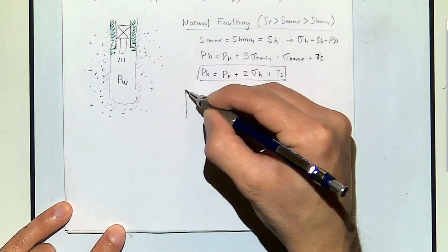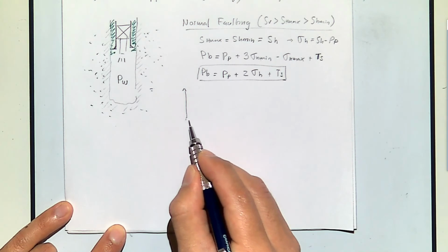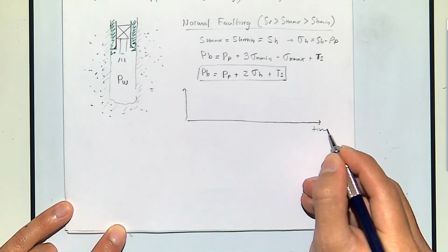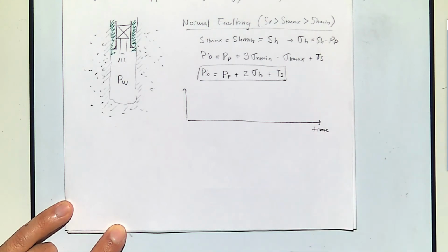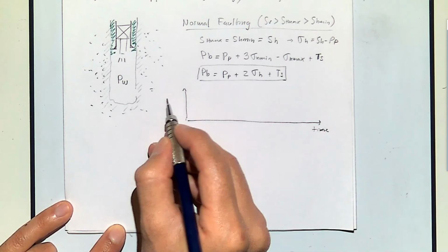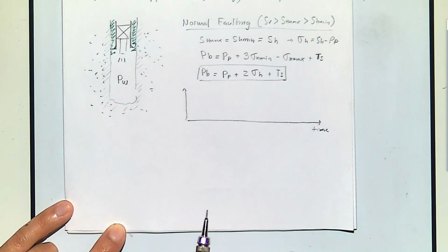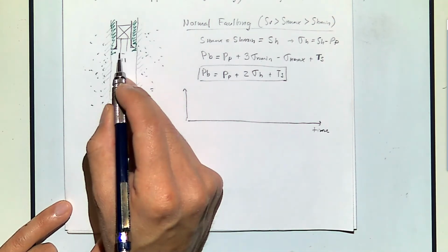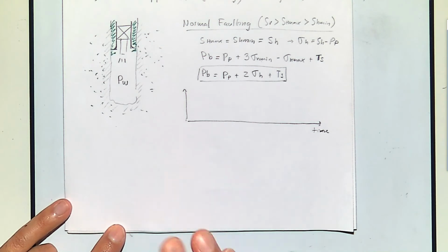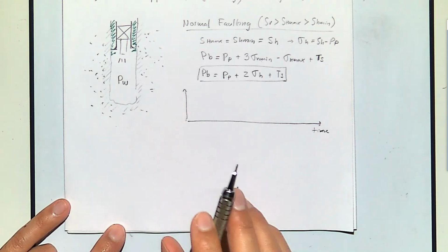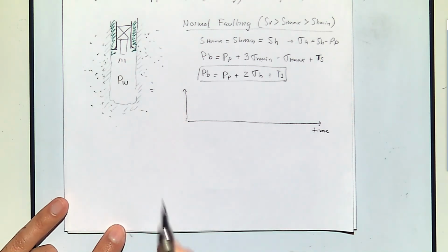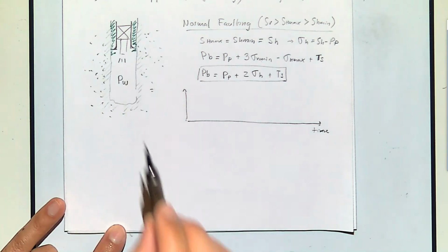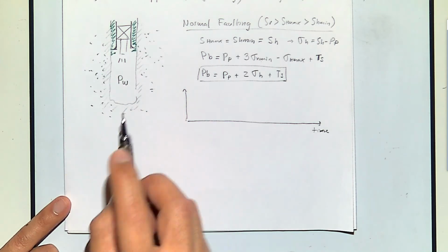In the leak-off test, what we're going to do is inject drilling mud into this open hole section of the wellbore under closed conditions. So we're just injecting, nothing gets out. In theory, or ideally, this should be cemented, so nothing should get out or escape from this cavity.